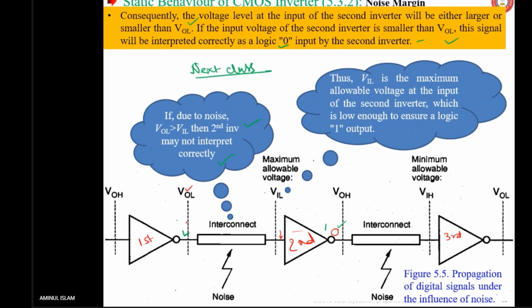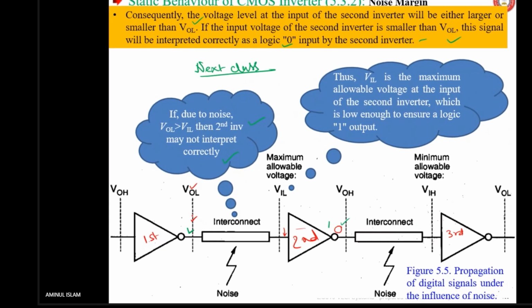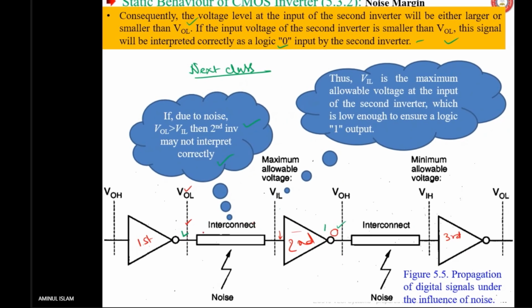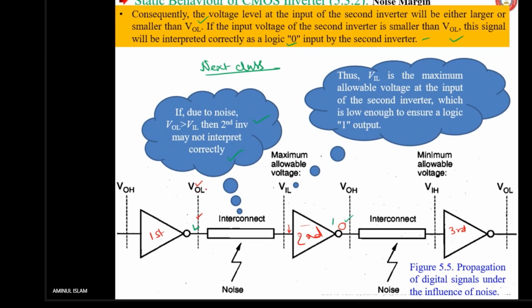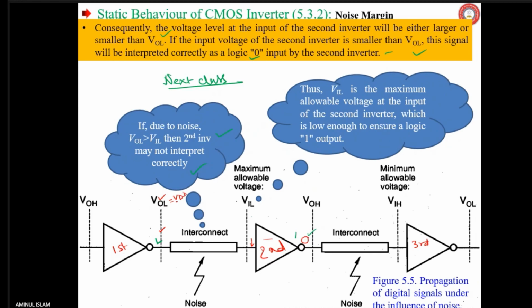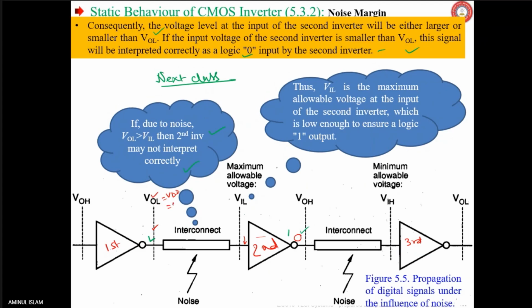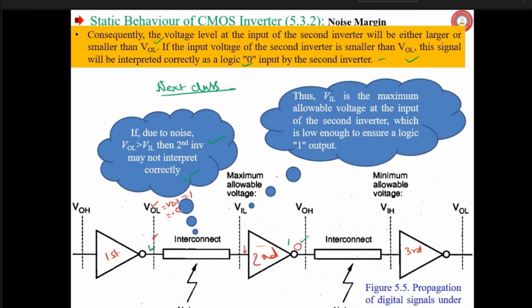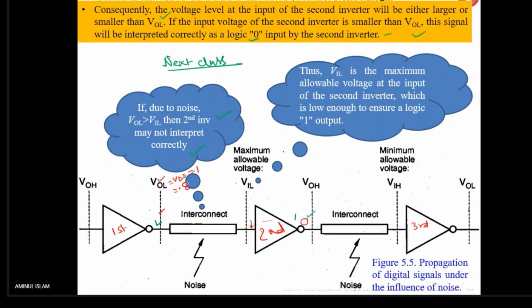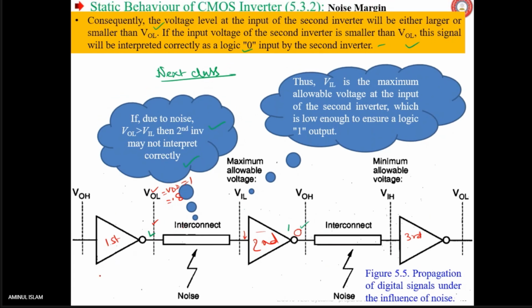See here, maybe VOL, but normally VOL, we have seen that should be, in case of CMOS circuit, equal to VDD only, but it may be a little lower than that also. Maybe say in a VDD equals 1 volt system, I am assuming 0.8 volt, and VTN equals 0.4 volt, VTP equals minus 0.4 volt.